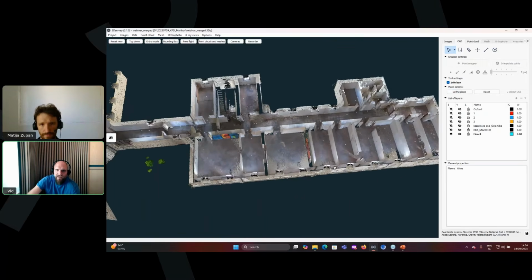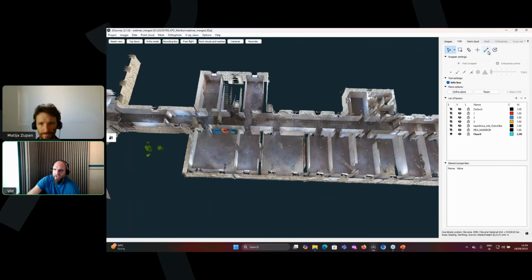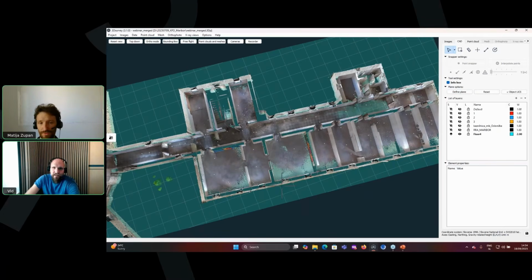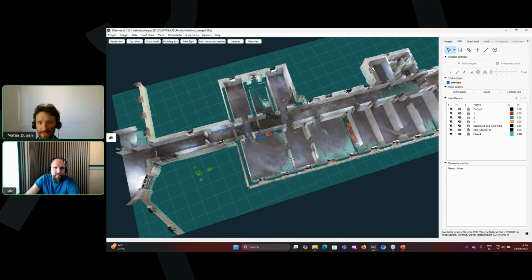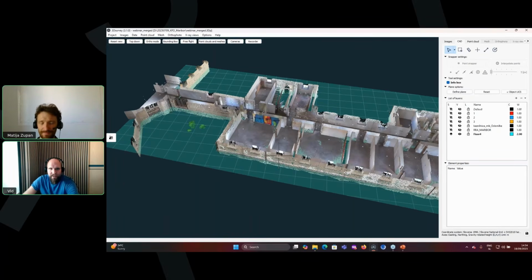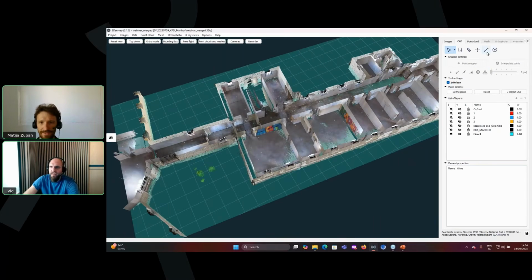First, we will define our floor plane. We go here and click define plane, and here we select an elevation in the middle of the main floor. Click to select. If we define a plane like that with 1 point, what we get is a horizontal plane. I will confirm this plane now. So now for the second thing. This plane basically makes sure that the plan I will create, or the whole floor plan, will all have the same elevation. Yeah, so it's locked basically. All vectorization is locked on this plane, on this height.